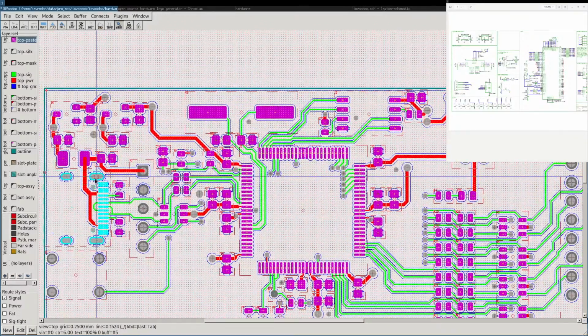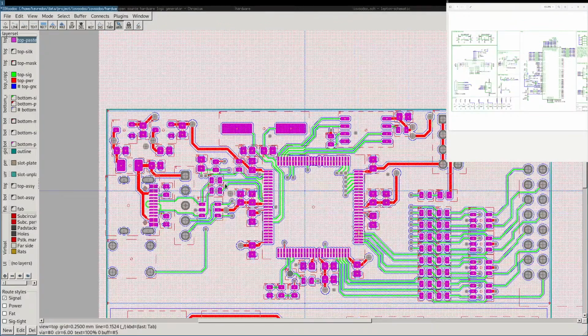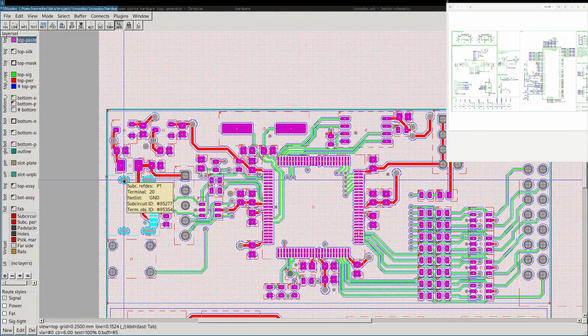So I could edit this pad stack and say, here you will also add some paste, so I can just do surface mounts for this connector. We don't care in our case because we will solder everything by hand. But for the production one, if I keep the same thing, I will probably edit it and add an opening here, so solder paste flows here.